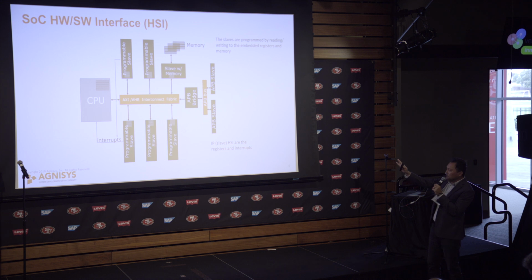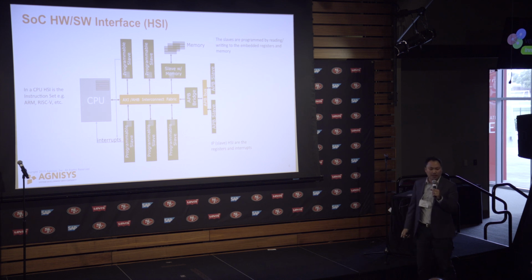In the interconnect fabric, there's the CPU on the software side, and then the IP slaves on the hardware side. There are a lot of embedded registers on the programmable slaves on the IP. On the software side, the HSI that we see is the CPU instruction set, all of those instructions from the software executing on the CPU. On the hardware side, there are the registers and interrupts, as you see here.